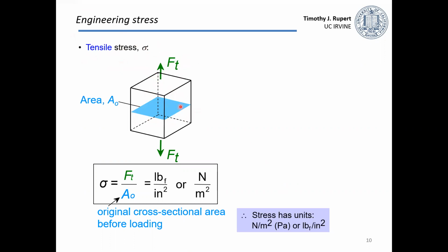And this is just done because you can imagine if I have a very skinny sample and I pull on it and I compare that with a fat and wide sample, it's going to take more force to destroy the wide sample. But fundamentally, that's just the geometry. I don't care about that. I want to think about the material itself. So the tensile stress is that tensile force divided by that cross-sectional area.